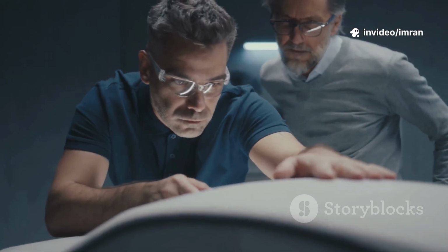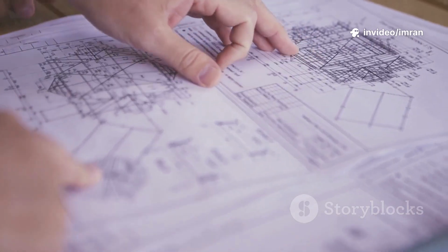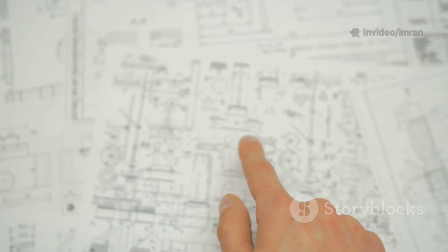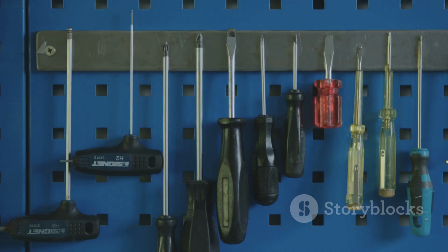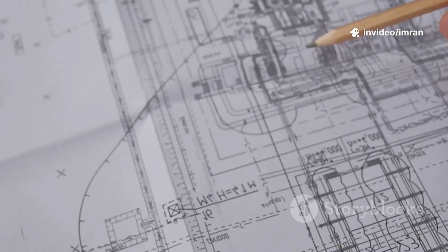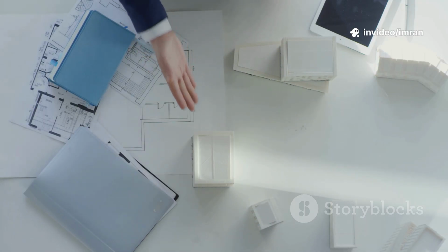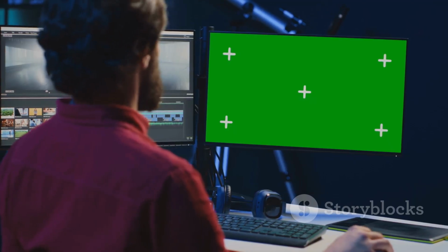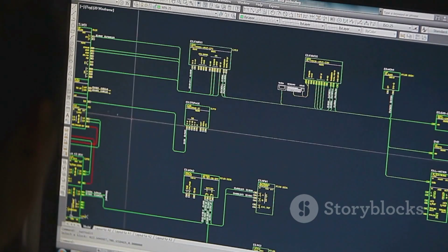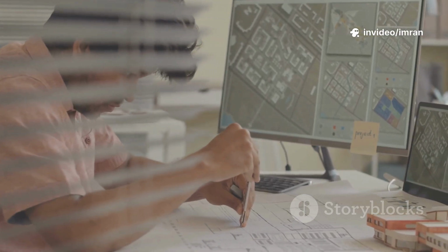The general workflow for most Modify commands follows a simple, consistent pattern: select, then act. First, you select the object or objects you want to modify. Then, you activate the desired Modify command to perform the action on your selection. Alternatively, you can start the command first, and then follow the prompts on the command line, which will ask you to select the objects. Both methods work, but as you gain experience, you might find the select first approach to be just a bit faster for many operations.